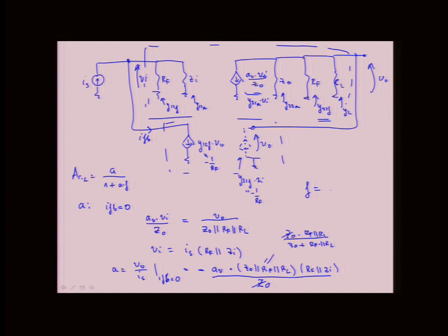Yeah, Y12 in general, and whether it's through the amplifier or through the feedback, right? We don't have one for the amplifier, because it wasn't in the model, we assumed it's gone. And so the only one that remains is Y12F. So our feedback is minus 1 over RF.